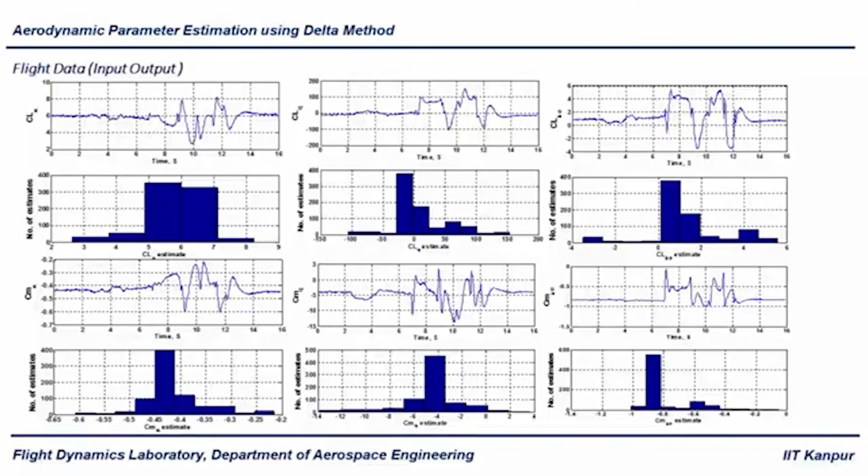And the next value is also quite prominent. Like that you can see the occurrence of all the estimated parametric values, how many times each occurred, and you can also take the average value, or select the value with the maximum number of occurrences, which will represent your corresponding aerodynamic parameters, right? So here it was about the CL and CM derivatives.